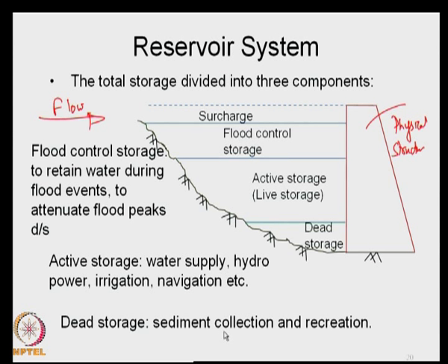So, the dead storage is mostly for sediment collection, and perhaps if you want to use this storage for recreation purposes, you may want to have a very high level of storage below which you are not using it. In fact, in some cases you also use it to build head for the hydropower. So, the dead storage is that particular storage from which you do not withdraw water. This amount of water is always there, that is what is called dead storage.